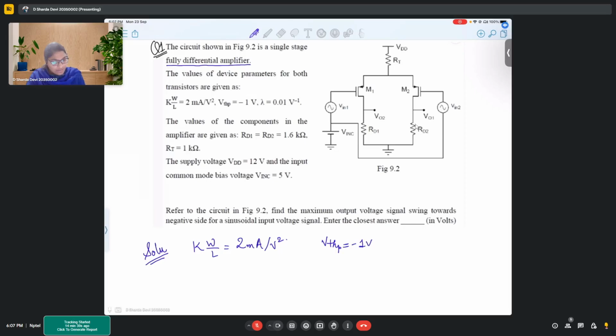Keep in mind that the differential pairs which are designed are always matched pairs. Practically that is not possible, and that's why you get the CMRR, or the common mode gain. But theoretically they should be ideal, like matched transistors. So all the transistors that you use in the symmetric pair should be similar.